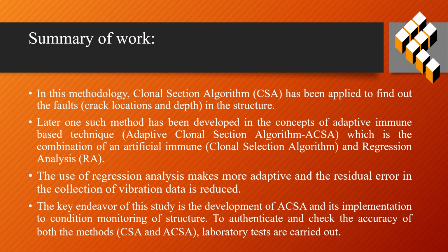The main objective of this study is the development of the ACSA and its implementation to condition monitoring of structures, that is to identify the crack location and to measure the crack depth. To authenticate and check the accuracy of this method, that is the CSA and ACSA, experiments are carried out in the laboratory.